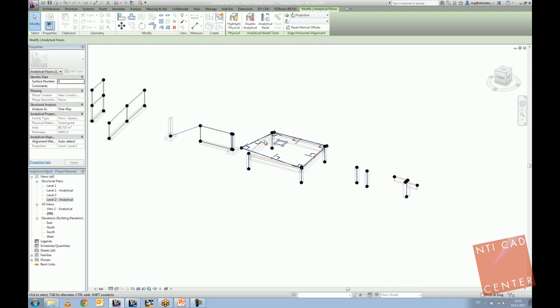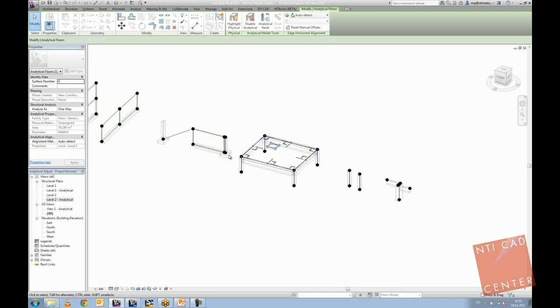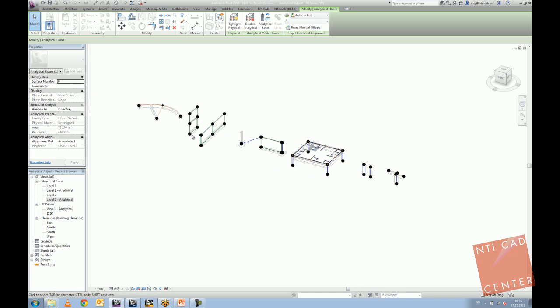Those are really powerful tools, Analytical Reset, using walls and so on, which allows you to modify your model. And again, it's as free as it never was before, because earlier you had just part of the options I've showed you going for properties. Now, in any case, if something is not achievable, you can always do it with this Analytical Adjust mode.